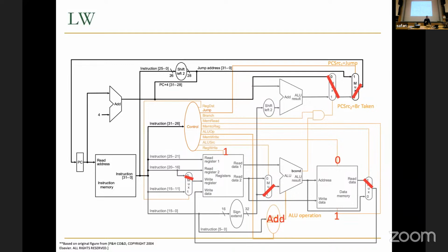So store word is very similar to load word, except a few things change. Basically, remember what we said is you invert what you do in memory, you store, not load, and you don't write to the register file. So these control signals get negated, as they did. And some things we don't really care about. We don't really care because we're not writing to the register, right? Store word doesn't write to the register.